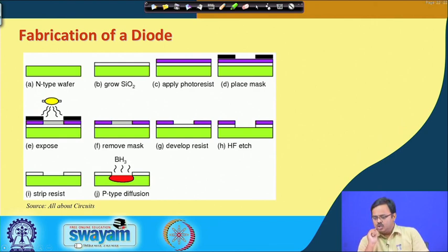Okay. So if we add a layer of photoresist, then we put a mask. And this is positive photoresist, where we will put this mask and then shine UV light, so that the part of the photoresist which was exposed to UV light can be removed. All right. So it undergoes a change in property, and then later on we can remove that photoresist from the area which was exposed to the UV light.